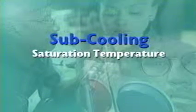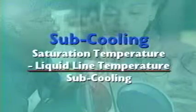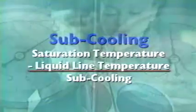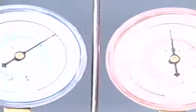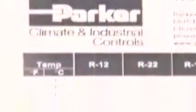To determine the amount of subcooling, use this formula. High side saturation temperature minus liquid line temperature. Determine the saturation temperature of the high side by taking the high side operating pressure and converting it to temperature using the PT chart.